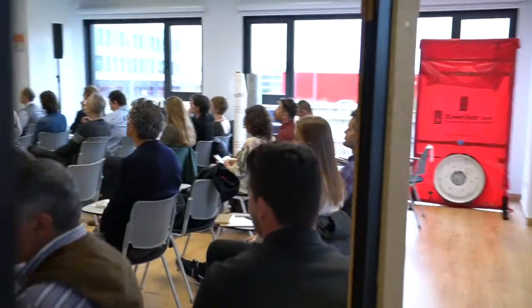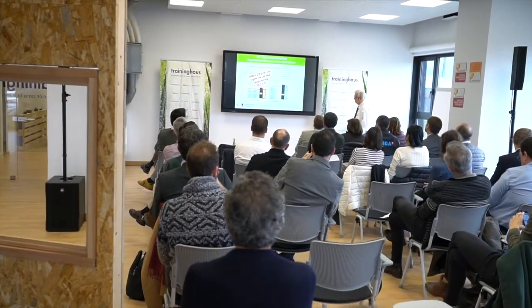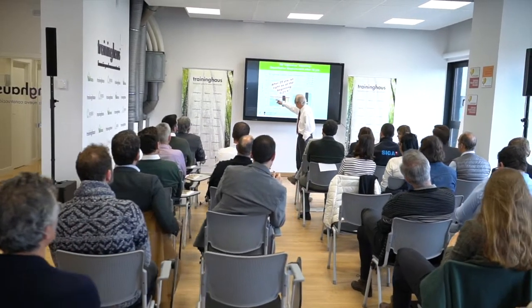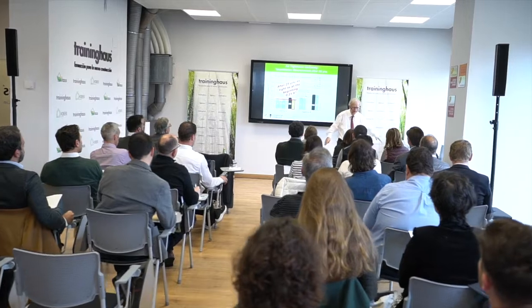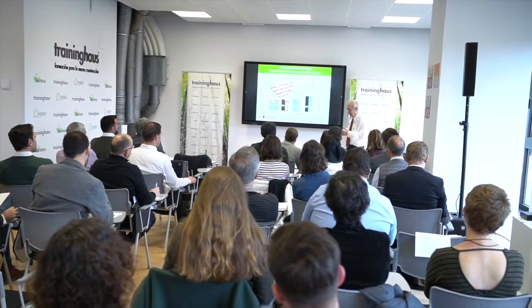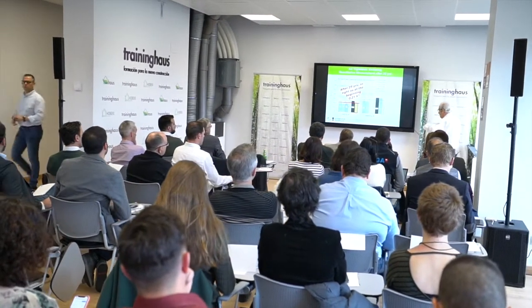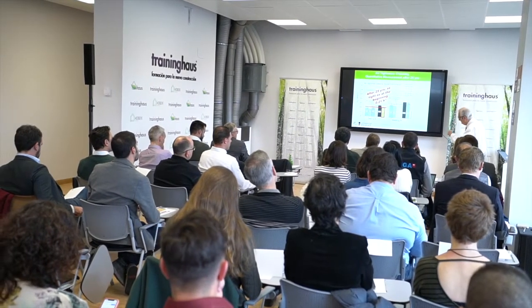So this is the airtightness measurements after 25 years of occupation. And what you see in the range of accuracy of these measurements, they also have a range of accuracy. You have a little bit of wind going, you have installed the blower door in different ways, the windows have been closed in a different way.